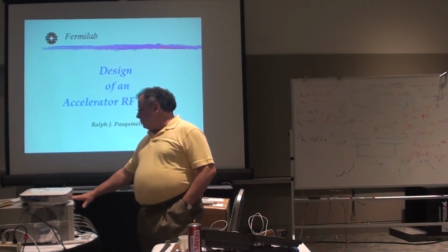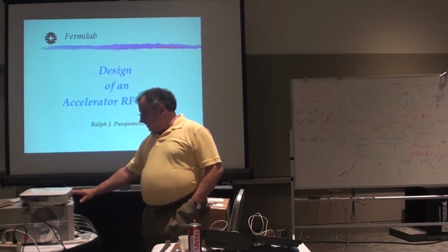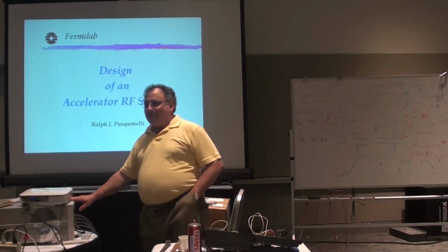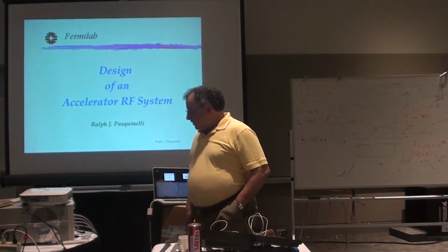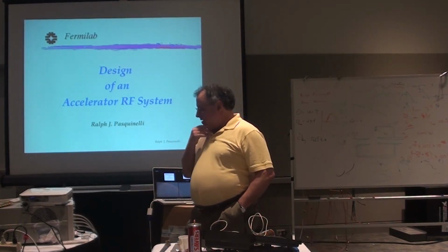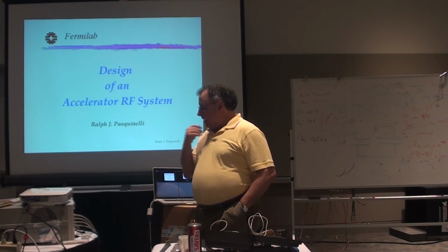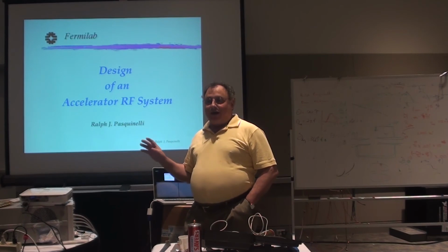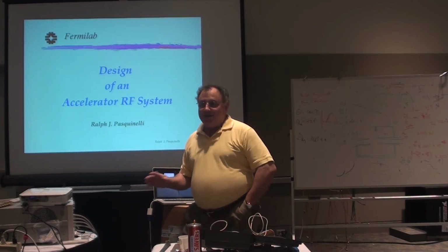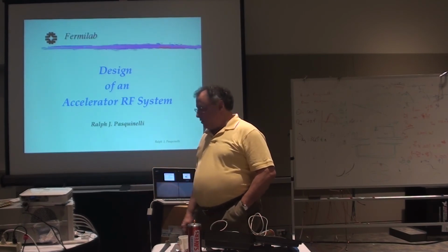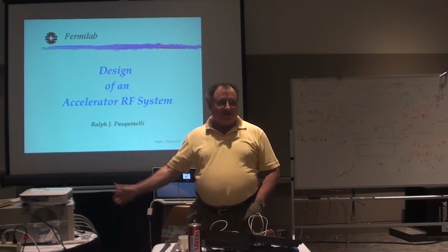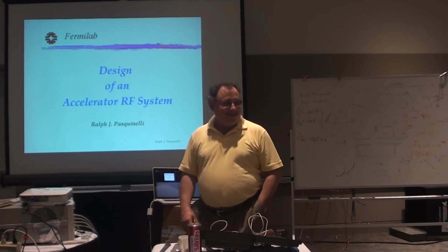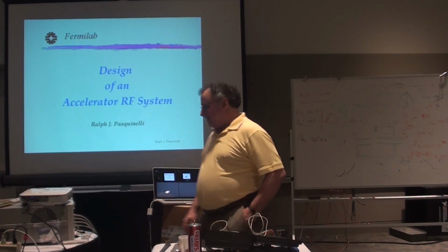I got both TDRs up and running, and these are the fanciest, schmanciest things I've ever seen. Ergo, also not so easy to use. But they're also the fastest one. They're like 10 picosecond rise time with incredible resolution. And they have 4 channels, which basically makes this a 4-channel time domain network analyzer. And so it has an incredible amount of capacity. Normally we just get a TDR or a TDT, but this thing is a 4-channel TDR, TDT. It can just do a lot of stuff.